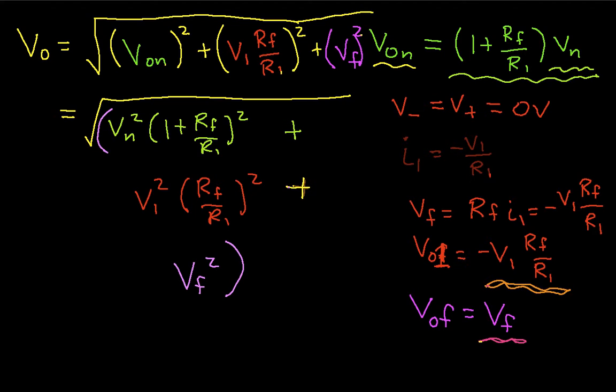V1 and VF we get using the square root of the formula for the thermal noise power generated by R1 and RF. So that's pretty much it. You can go through and work these for several different examples and see the relative weighting, under different circumstances, for the noise generated by the op-amp and the noises generated by R1 and RF.